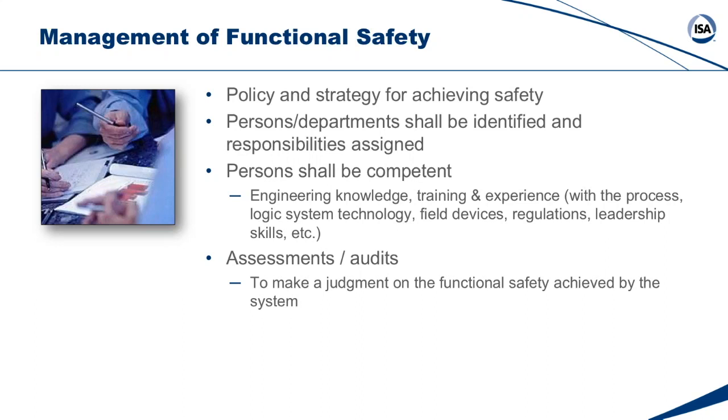You feel, hey, we need to start the unit up tomorrow, and we're all in a rush, and we have a schedule to meet. And the auditor or the assessor looks at these 36-inch valves that your specification says must close in half a second or less, but you just have a standard solenoid-operated valve with a 1/4-inch vent line, and that 36-inch valve takes a minute to close. And that senior competent person says, sorry, you can't start the unit. I don't care what your schedule or the cost is. That system is there for a reason, and it won't work.